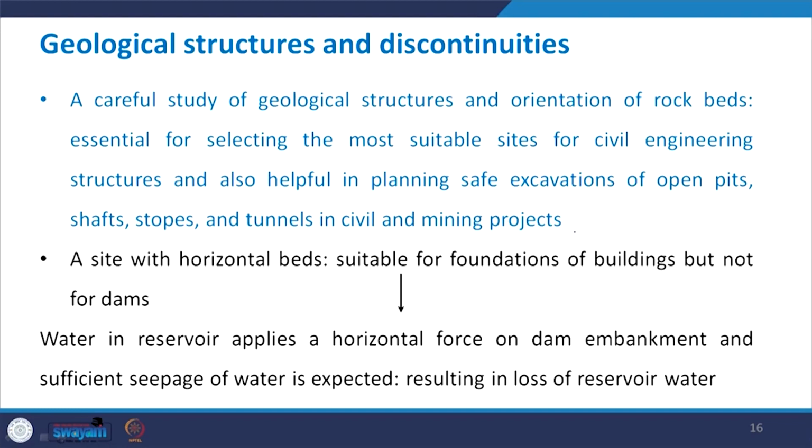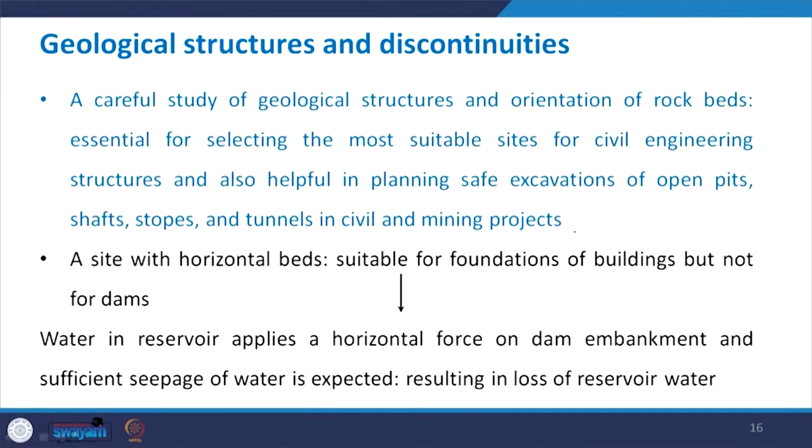The water in the reservoir will apply a horizontal force on the dam embankment, and therefore sufficient seepage of water is expected, and once that seepage takes place, there is going to be immense loss of reservoir water, which is not desirable as far as the functioning of the dam is concerned. So we say that horizontal bedding planes at a particular site are not suitable for foundations of dams.